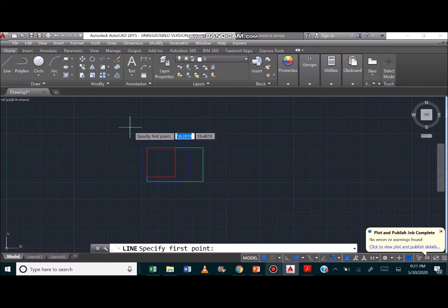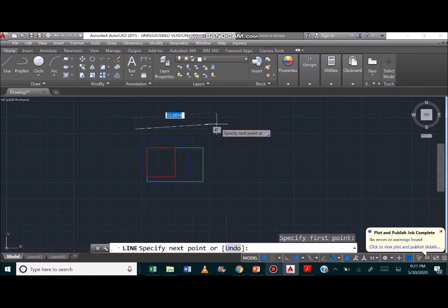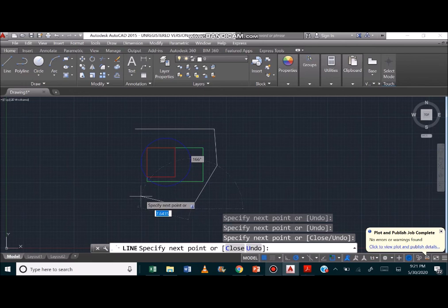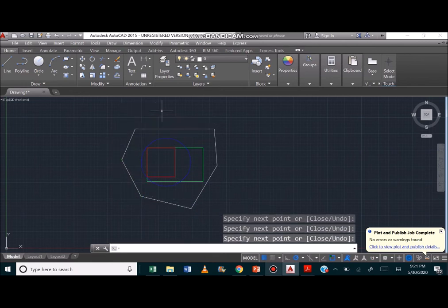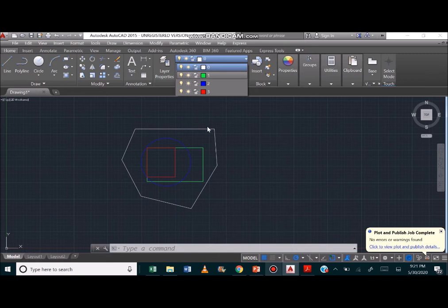The first one maybe I'll just make with white. So whatever white lines that you are seeing, they may actually be black lines whenever they are getting printed. So this is a 4 layer drawing, 0, 1, 2, 3. First layer, layer 0, is just this kind of polygon. The first layer is a rectangle, second layer circle, third layer square. So I want to plot it into a PDF, so simply I will write here plot.